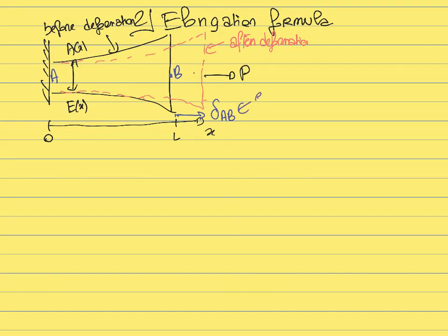This is going to give us the elongation, in the same way that we defined the elongation in the chapter on strain. With the notation that we will be using, the elongation should always be defined between two points. In this case, this would be the elongation between A and B. To define the elongation, it needs to be a change in length, so we need to define between which points this length is initially defined, and what the change is between the distance of those two points. So we always need to define two points like this when we define an elongation.